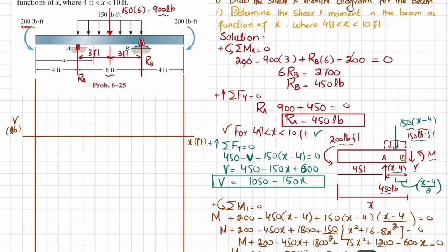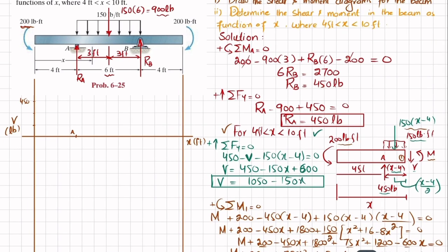Now you can see at this point there is no shear force, so from this point till A, the shear force will be the same, 0. This is your point A. Now at A we have RA, which is equal to 450. So let one division be 150, 250, and this is 450. So shear force will change from this till this point.